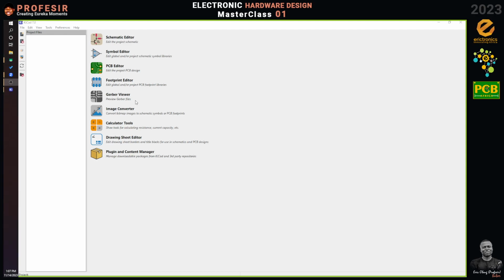It's a standard for PCB development. So you have to generate your Gerber files, and before you send them, it is sometimes good practice to inspect them. This Gerber viewer can help you preview your Gerber files before you even send them to your PCB fab house or manufacturer.